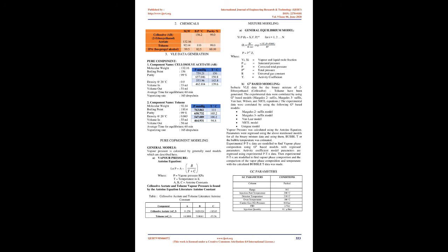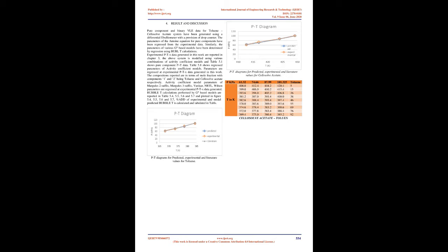The basis of distillation is phase equilibrium, specifically vapor-liquid phase equilibrium, VLE, and in some cases vapor-liquid-liquid phase equilibrium, VLLE. Distillation can affect a separation among chemical components only if the compositions of the vapor and liquid phases that are in phase equilibrium with each other are different. A reasonable understanding of VLE is essential for the analysis, design, and control of distillation columns.